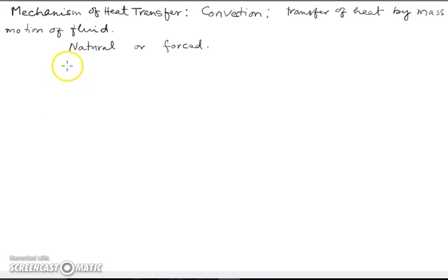So P convection is directly proportional to the surface area. This is the reason for the large surface areas of radiators and cooling fins.